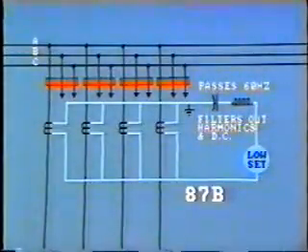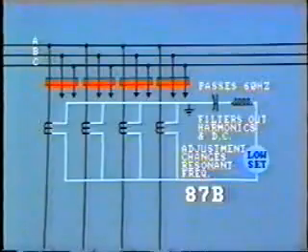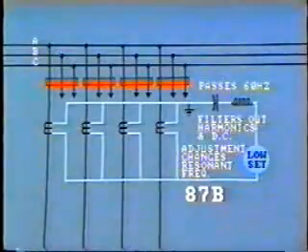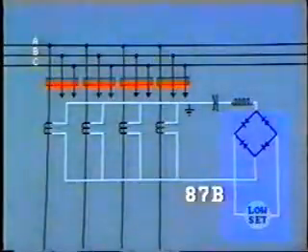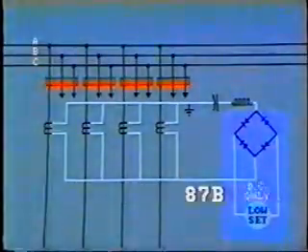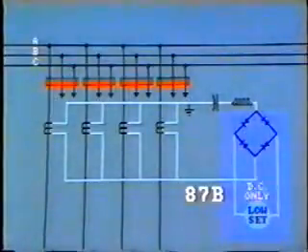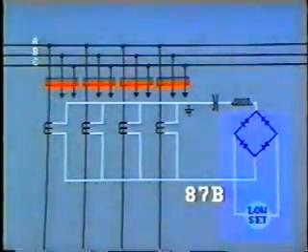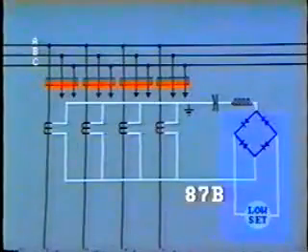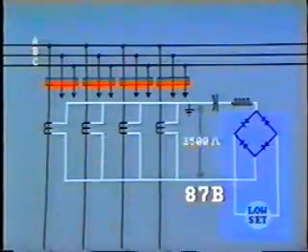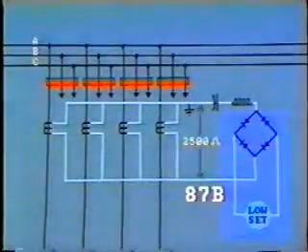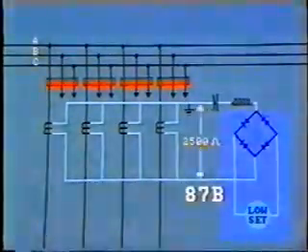One problem with this arrangement is that when the setting of the relay coil is adjusted, it changes the inductance in the circuit and so changes the resonant frequency. In order to avoid this, a rectifier is placed in the circuit so that only DC current is fed to the relay operating coil. Now, adjustment of the coil will in no way affect the inductance of the tuned circuit. The effect of the rectifier and the resonant circuit raises the total impedance across the relay at this point to quite a high value, usually around 2,500 ohms.